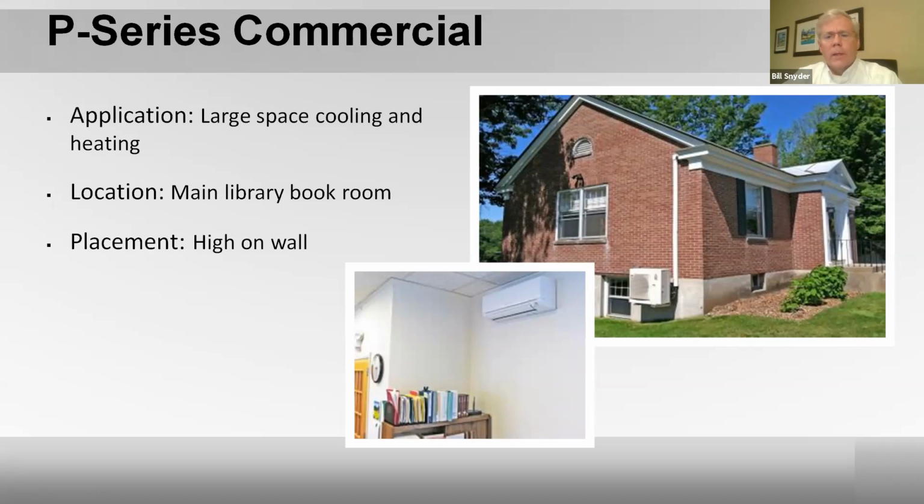So if you put it in the bedroom above the master bed and you have 6 feet of line going to the outdoor unit, they probably will hear something. So I would recommend getting at least 16 feet minimum line length. That helps on the noise issue.